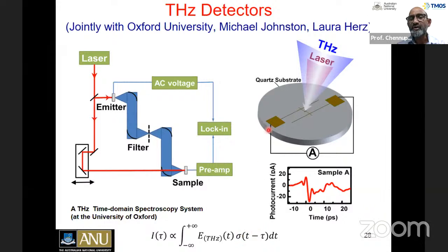In fact, we started looking at this as terahertz spectroscopy to measure the electrical conductivity of the nanowires without making any contacts. But then we asked ourselves, can we really detect terahertz radiation using single nanowires? Because terahertz radiation is about 300 microns in wavelength, but we are really dealing with 200 or 300 nanometer diameter nanowires, about 3 or 4 microns long.